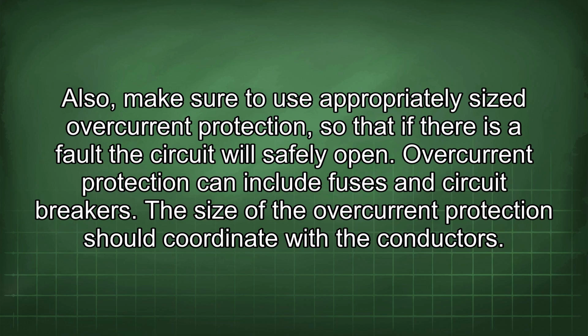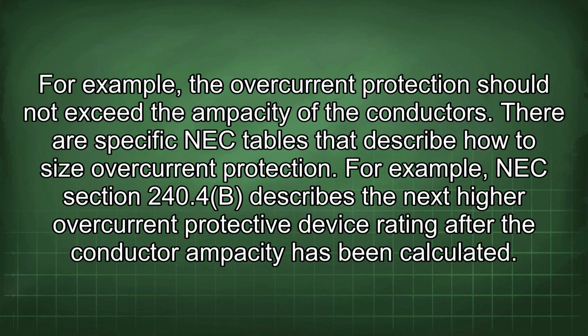Also, make sure to use appropriately sized overcurrent protection, so that if there is a fault the circuit will safely open. Overcurrent protection can include fuses and circuit breakers. The size of the overcurrent protection should coordinate with the conductors. For example, the overcurrent protection should not exceed the ampacity of the conductors.